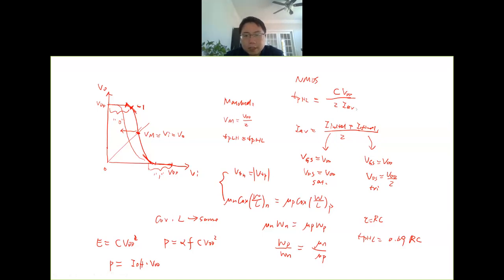So you still need to satisfy the matched condition, those two conditions together, to make it totally match. You should have VTN equals VTP and also the second term here. You need to satisfy both to get the matched condition where you can get the same noise margin for 0 and 1. So you have to satisfy both.